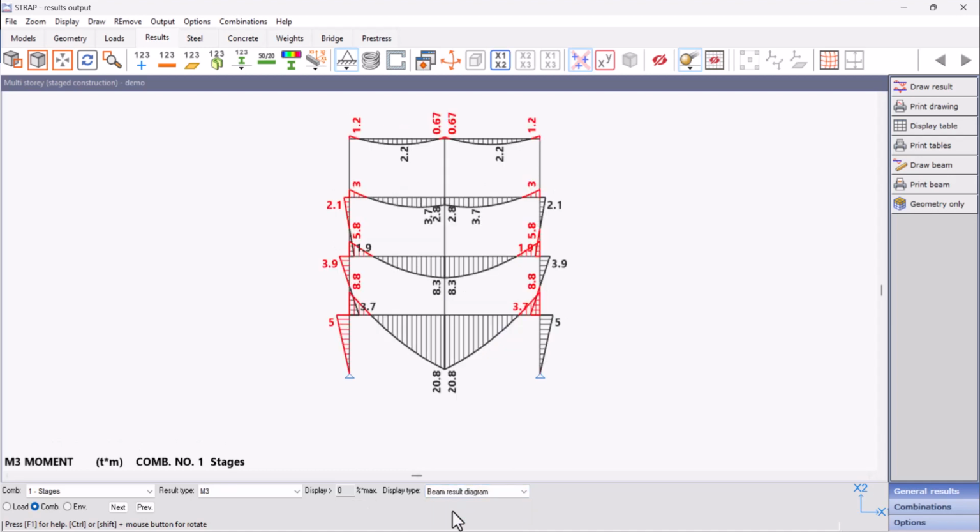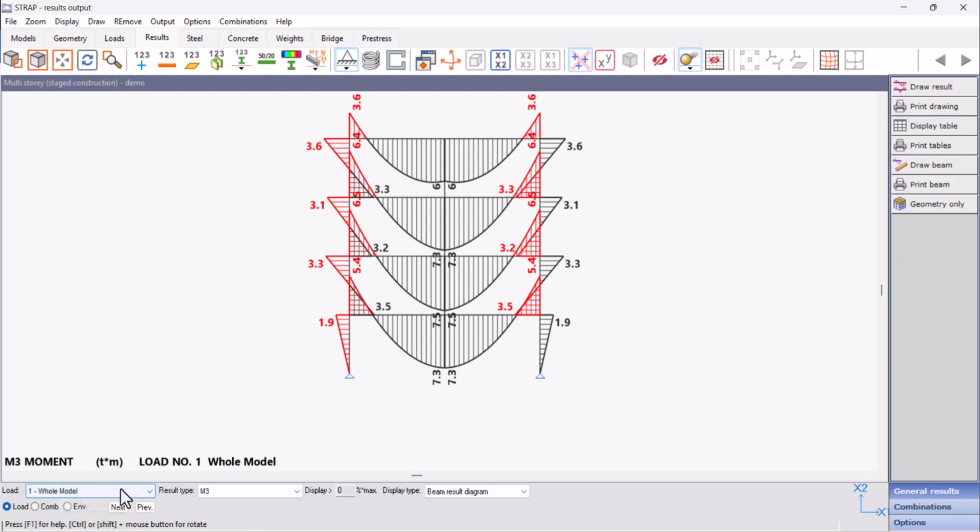Notice the differences in the bending moment diagrams between the floors. There is a significant variation in the values between the bottom and top floors, in addition to the displacement as mentioned before. By contrast, the structure subject to global loading exhibits similar bending moment diagrams across its floors. This disparity occurs due to the fact that the structure was loaded only after its construction was complete. As was explained before, the difference stems from the application of loads on different static schemes.